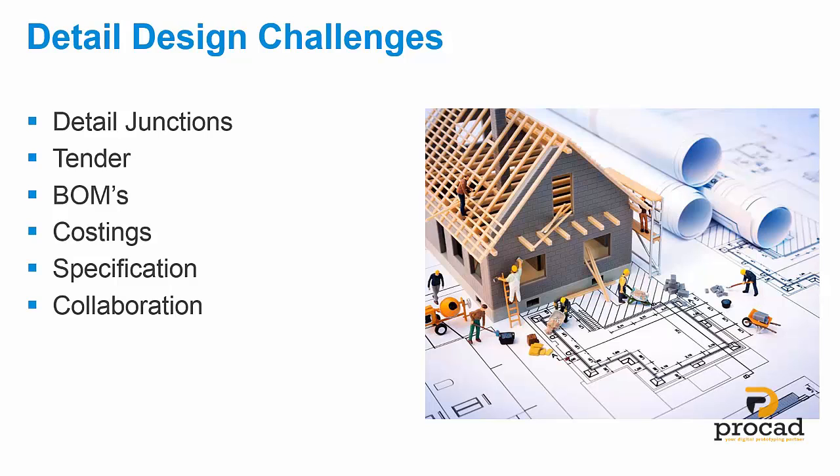You can also further enhance that information by adding cost to it, adding a cost to a door. This door costs X amount. If it gets deleted, the cost of your project can automatically get updated as well. And you can even output that information again to Excel and share that if there's a quantity surveyor involved, or link it back to your bill of materials as well.